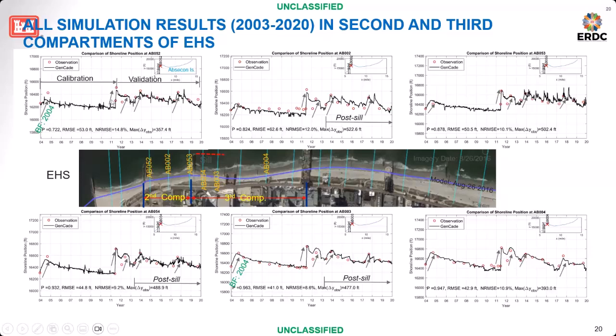And the arrows, most of the jumps, indicate one beach fill event based upon historical data of beach widening. So you can have your calibration period over 80 years and another 80 years for validation. We don't have that kind of clean validation, because during the validation, structures still keep changing. So you still need to tune the parameters about the structure during the validation, but mostly you keep the calibrated K1 and the validated depth of closure. So it looks like pretty good calibration and validation results.